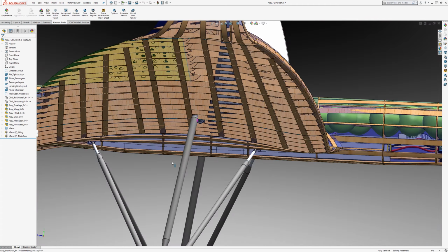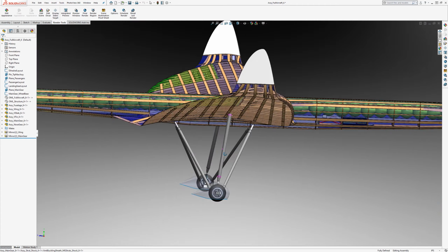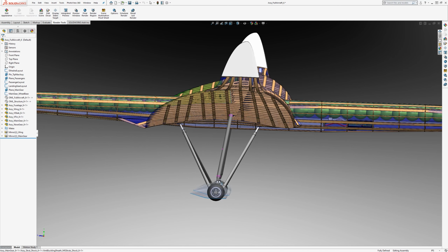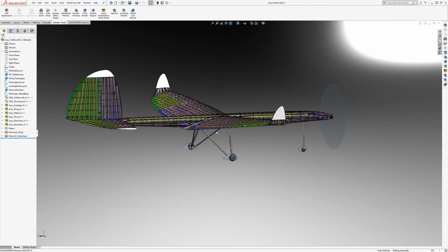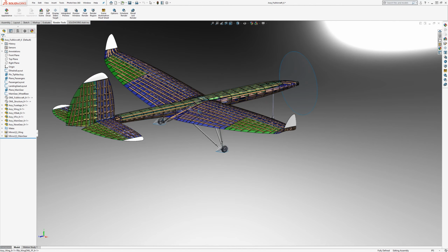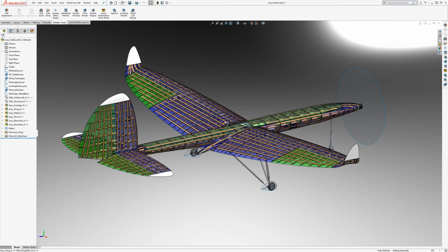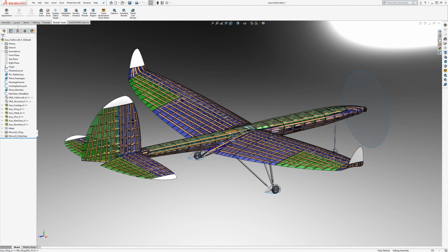And other than that, you would just really need to know for what's in between those two ends, you'd mainly need to know the mass properties and the suspension properties of the landing gear. So at this stage of the initial loads calculations, you wouldn't need an aircraft that looks as finalized as this.